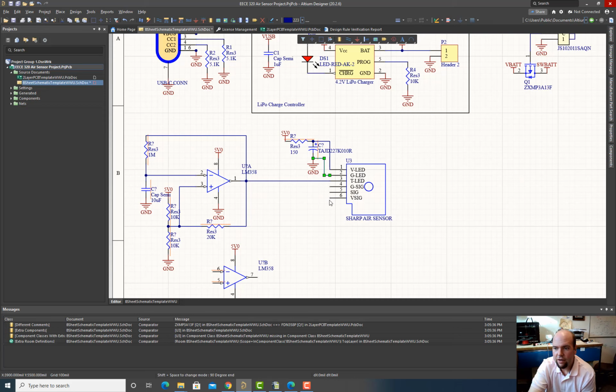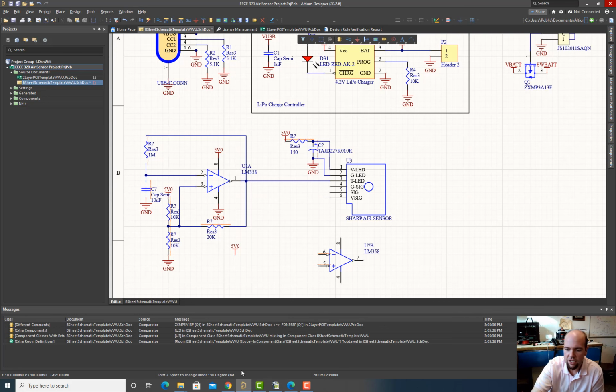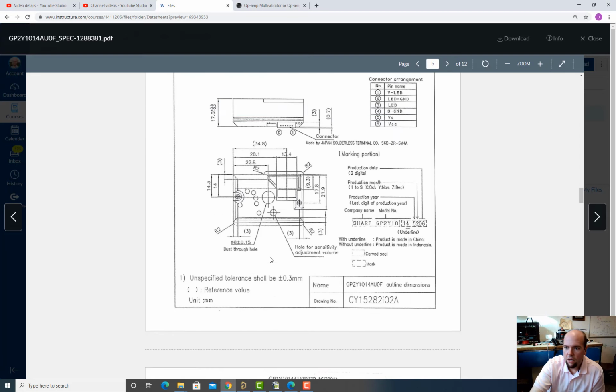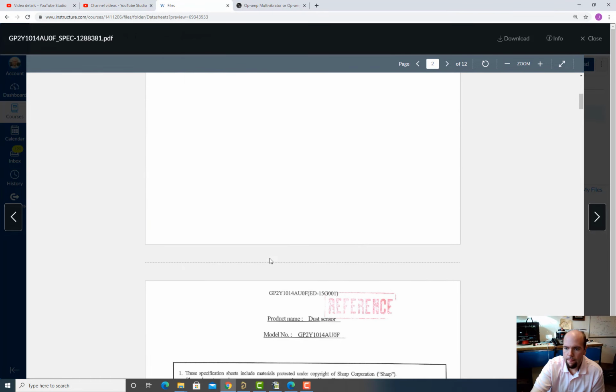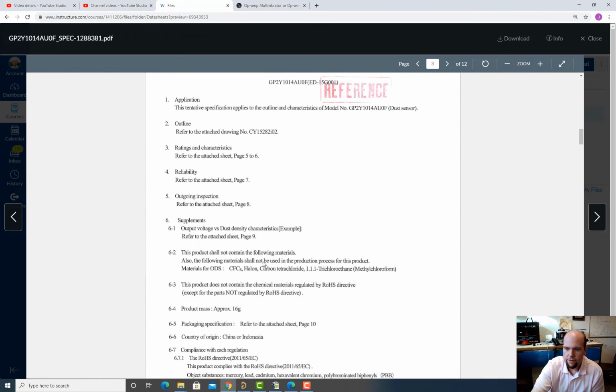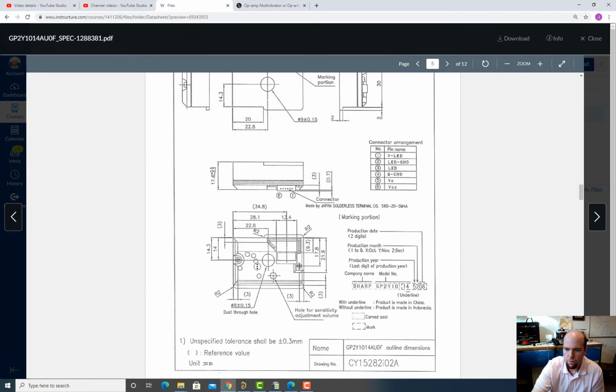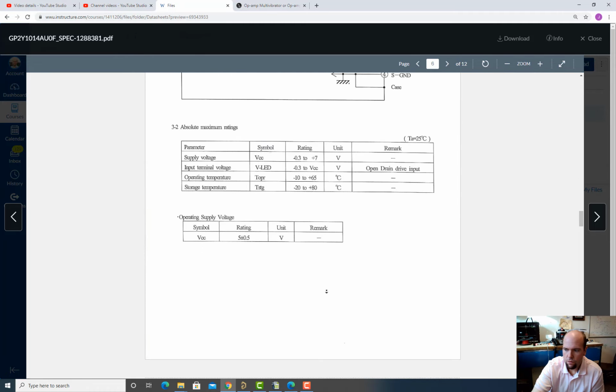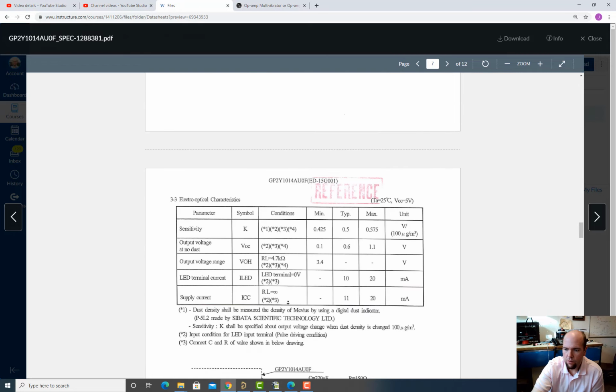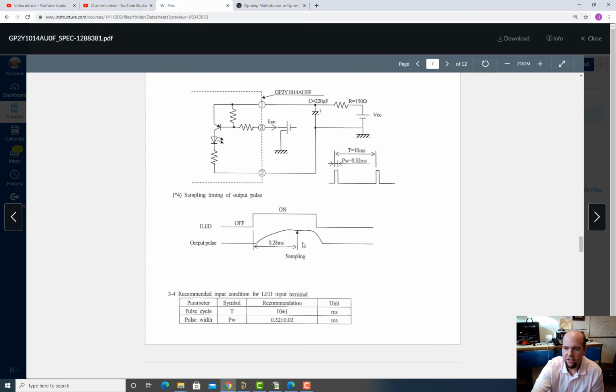And then, okay, yeah, let's just go ahead and do the output now. So the output comes in pulses. The output comes in these little pulses that we showed in the data sheet. So there are these little pulses, right? And that's not a great shape for a signal. It's not very useful. So what we're going to do is add a peak detector to that.